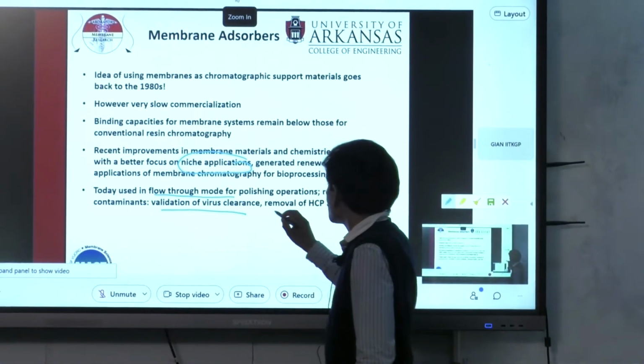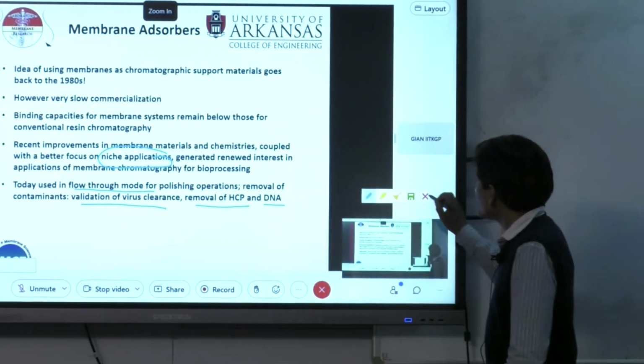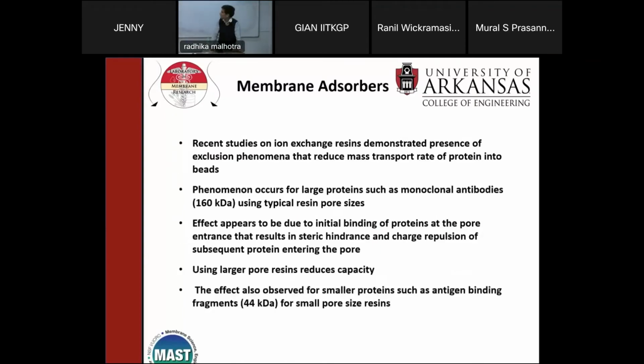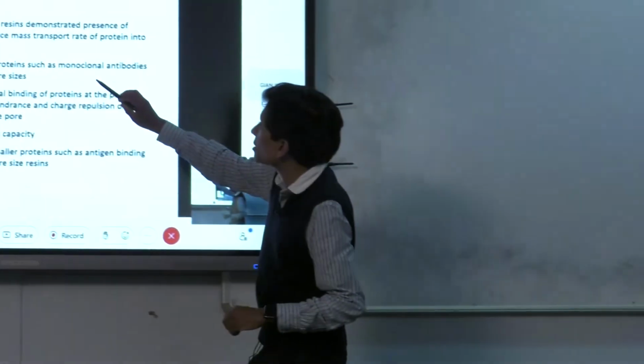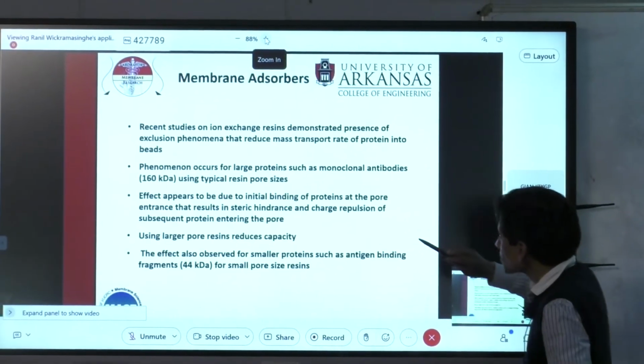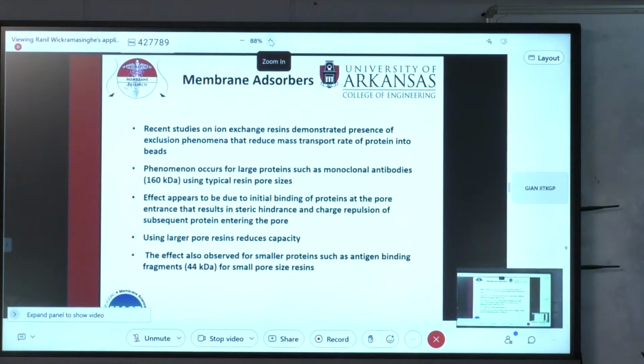So viruses, host cell proteins, HCPs, and DNA. So until we started thinking about membrane adsorbers in terms of flow-through mode, they were never competing. But today they are found to be very, very effective for this. So recent studies on ion exchange resins demonstrated the presence of exclusion phenomena that reduce the mass transfer rate of protein into beads. So that's one thing to note.